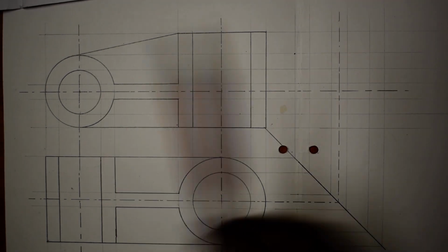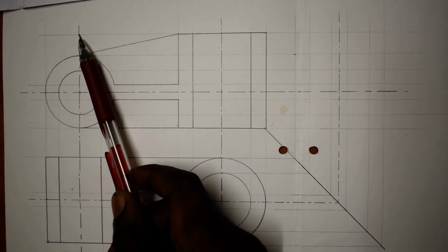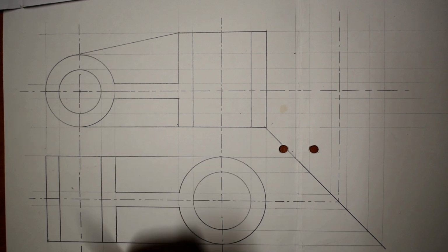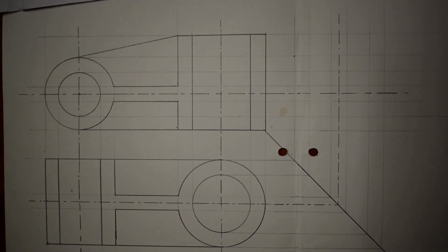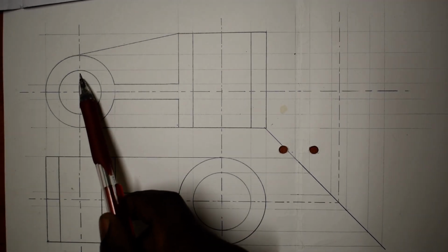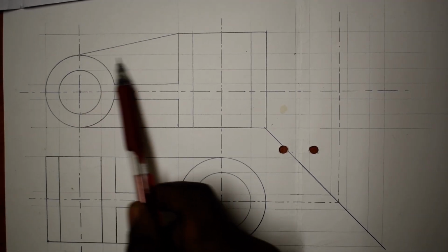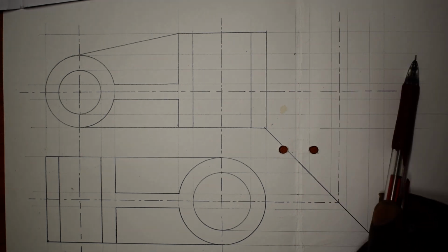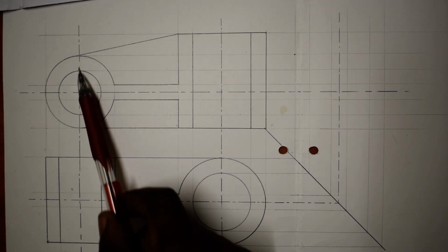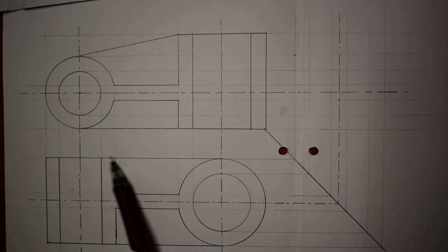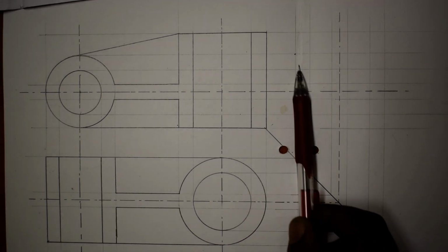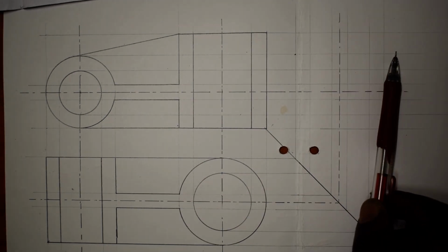Let me repeat, how did I get it? The hacksaw started to cut from here, isn't it? From here till here it didn't cut it. So we focus on what the hacksaw is cutting at the moment. You get it? From here till here it cut it. So trace this point horizontally. Then trace it to your top view. Once it touches the 45-degree line, it goes up and will intersect with this one.